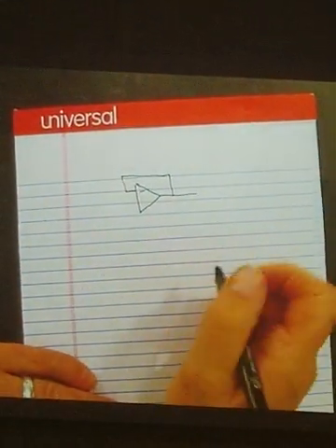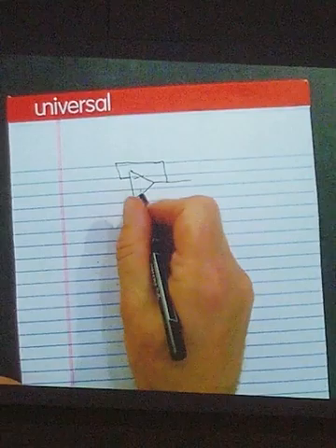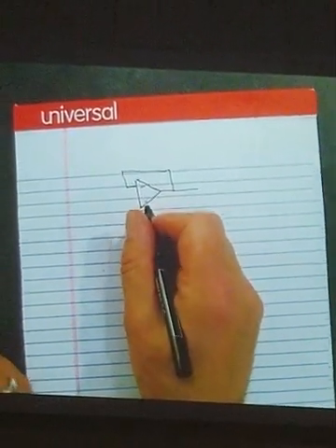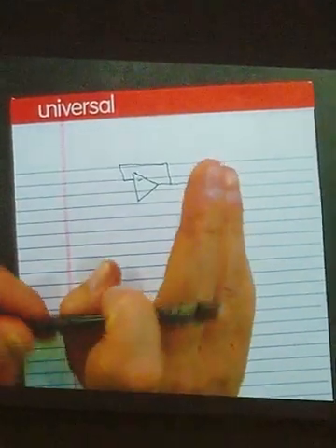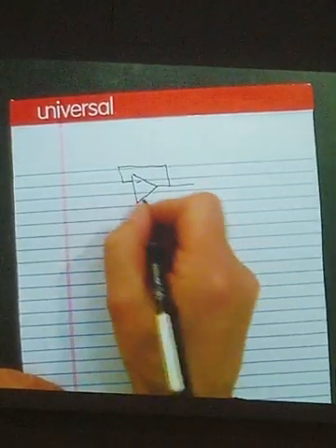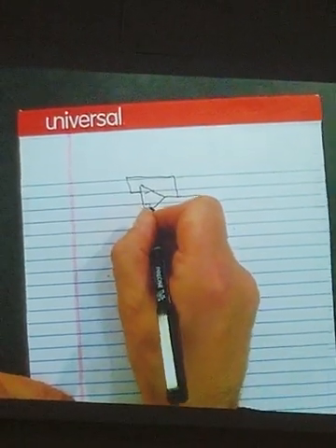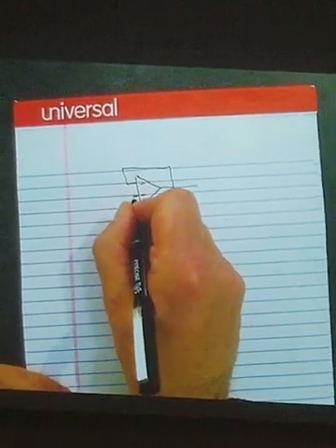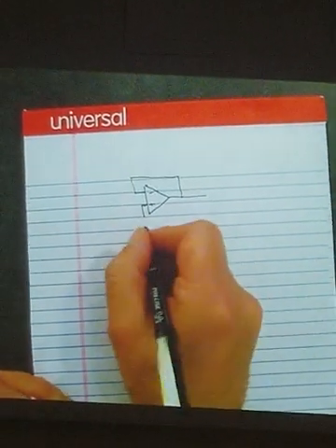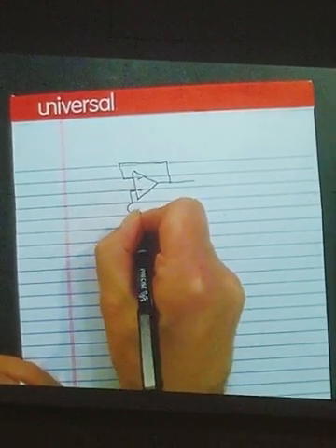Anyway, so instead of thinking of the individual contributions of every little noise source and every little transistor, and if you want to learn a little bit about how complicated that is, take W4111 from me. But we just tend to think of it as a fictitious source applied to the input.